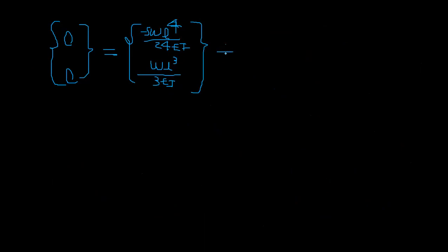And then we have flexibility coefficients. Remember, it's L cube over 6EI. This L cube, L to the power 3. So this was L squared over 4EI, L squared.